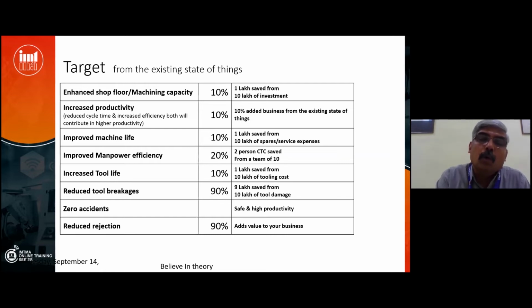Suppose you have 20 holes, it is better to use better tools which can run at higher cutting speeds and feed rate, so that I can reduce cycle time. Suppose you have only 2 holes, or only 1 hole. Then what do you do? Don't use costly tools there, no use, because 1 hole for 20 mm deep may take maybe 12 seconds. If you use a costly tool, it may take 8 seconds. But instead of a 600 rupee tool, you use a 6,000 rupee tool. Unnecessarily, you are increasing your inventory. It's not required, basically.